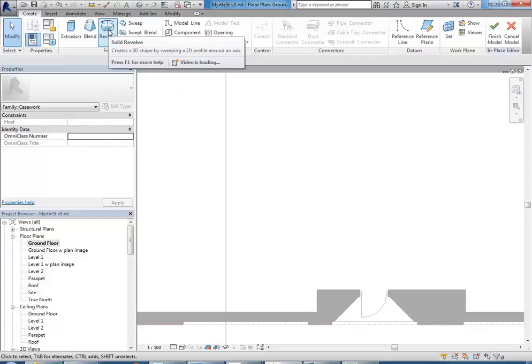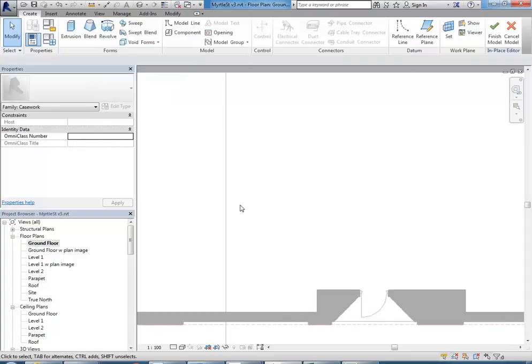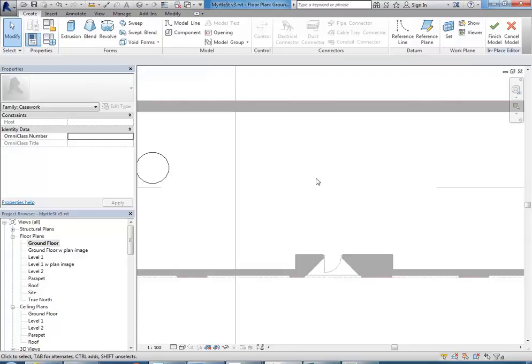So have you used Revolve before to make anything? No, okay, right. I tried to. Yeah, so the key to it is knowing how the planes work, because you need to work in different planes. So here, I want my column object to sit about there. And it's going to be a circular object. And so to make it there, I need to have a plane defined. With Revolve normally, if I just make it in the ground floor plan, it's going to, well, I'll show you.